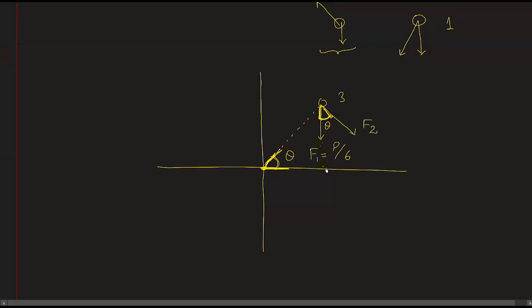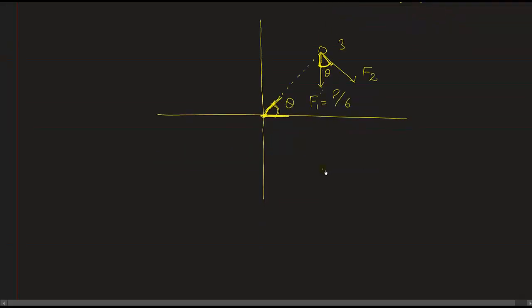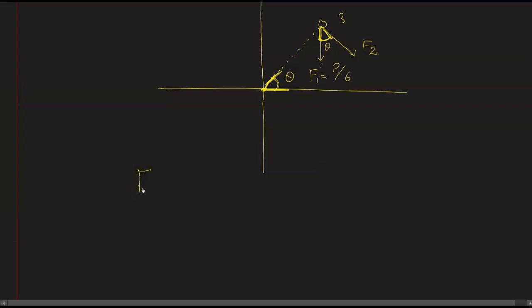Now we can calculate the resultant force, but before that we have to calculate the force in bolt number 3, that is F3 is equal to P times E divided by summation di square, multiplied by d3. This distance is given in the problem.